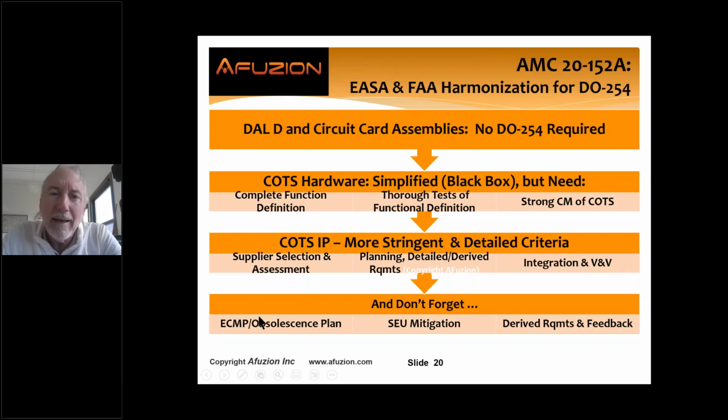We need an electronic components management plan, not for software, but for hardware, ECMP. How do we manage all of our hardware devices, our COTS IP? How do we mitigate single event upsets? And how will we feed back, just like software, derived requirements to the system process to show it's safe?